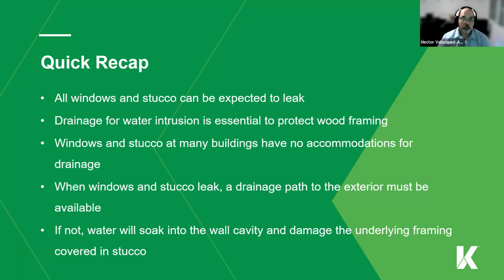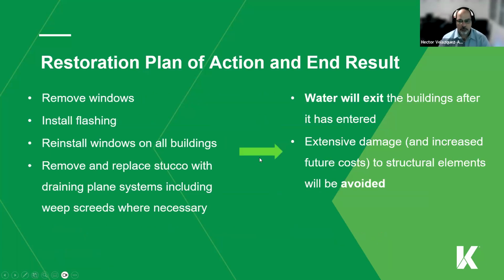Your vents for your dryer also sometimes cause problems. On your roof, your flashing causes problems. Make sure that you get all that water out of your building. If the piping is the issue or my AC is the issue, make sure to fix it, to address it. Keep in mind that the Florida Building Code requires you to have an evaluation of those pipes and to evaluate who's doing the lining. When you do the lining, that has to be reviewed, typically by the city.